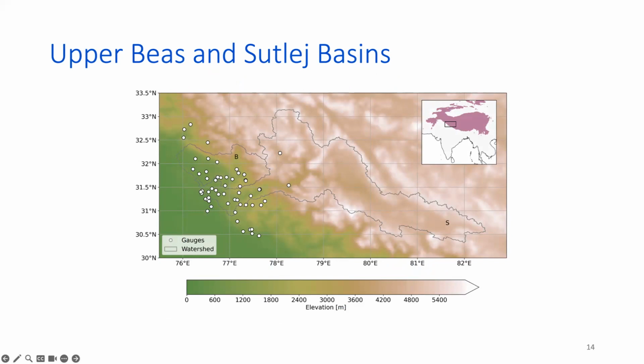Here we have a network of 58 rain and snow gauges, which have been active for at least 5 years between 1980 and 2013. And we would like to use multi-fidelity Gaussian processes to combine some model data with that of the gauges. We want to learn the mapping between the inaccurate but complete model data and that of the sparse but accurate gauge data in order to make predictions in this area here where we have no measurements.